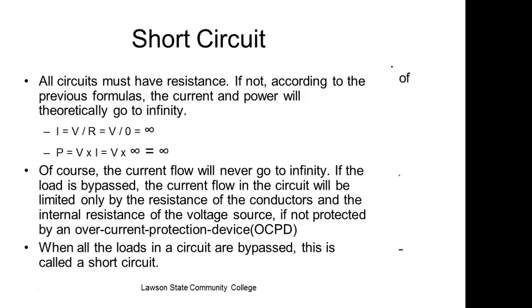So to do math in these early computers, we had to write a program to do math. And what you do for division is use what we call repetitive subtraction, which is what division is. We take what we want to divide in, and we start subtracting what we want to divide by, until we generate a borrow, which means we exceeded the number. How many times can you subtract 0 from a number without borrowing?